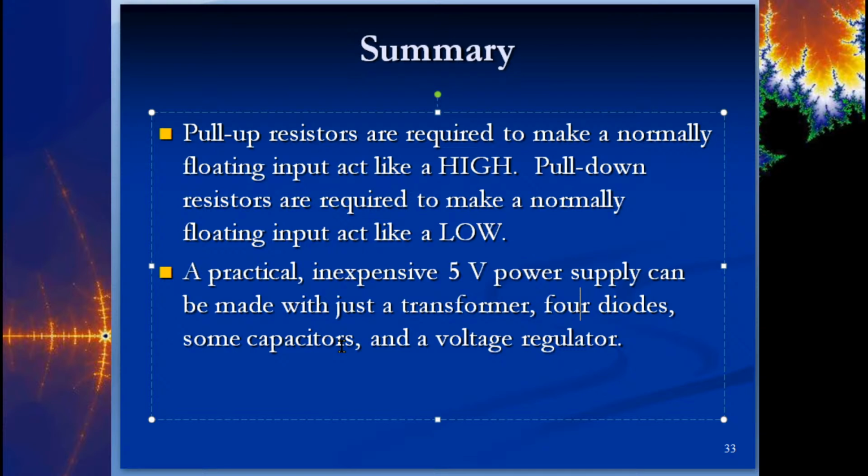So it could be used to power your IC chips if you wanted to buy some TTL chips and some CMOS chips too. All of those chips require 5 volts to operate. You could also use it to drive an LED, because an LED only needs a 300 ohm resistor and 5 volts to operate. So just some things to consider.